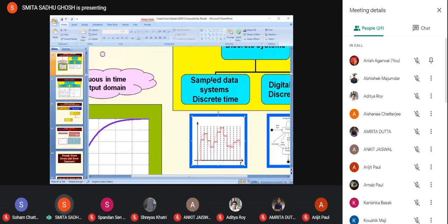Okay, so a sampled data system is a system where discretization has occurred along the time domain. There is no response between those intervals. If you were to find out what the response value is between those intervals, there are ways of doing it. Like, for example, I've joined over here. The value at 0 second has been extended up to 1 second, or rather has been held up to 1 second.